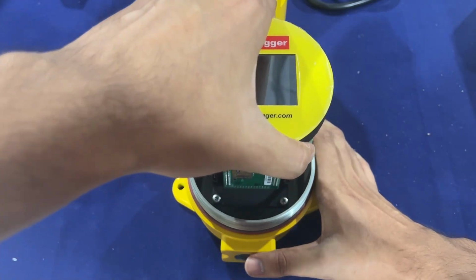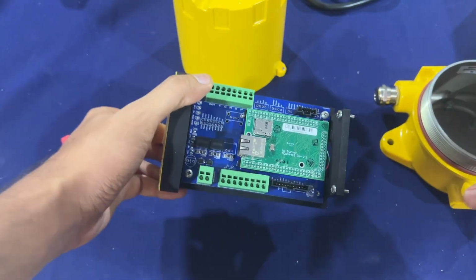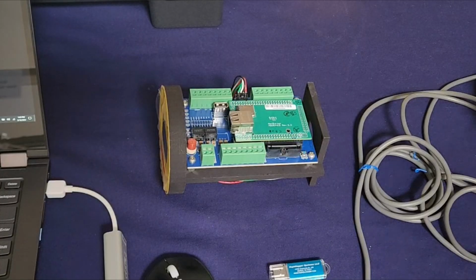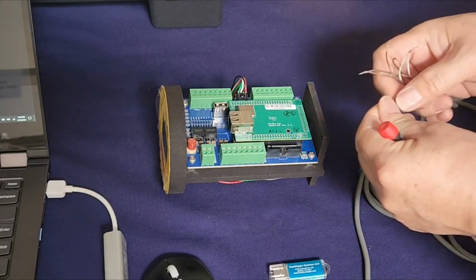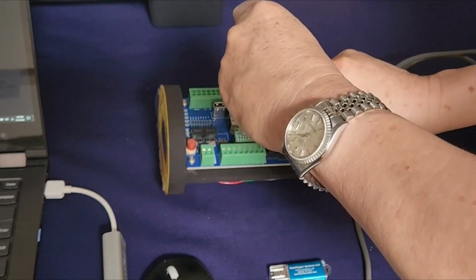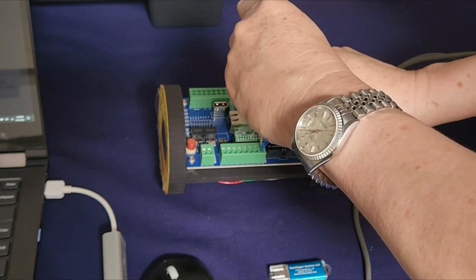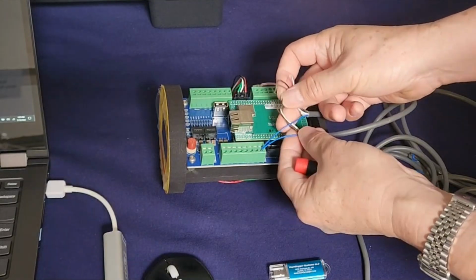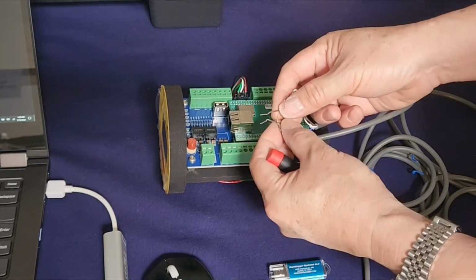Take out the Rapidlogger board and lay it on a workspace. Now, connect the encoder into the Rapidlogger ExD unit. To do this, connect the ground wire for power for both encoders into the terminal block J5-8. Then, connect the power wires for both encoders into the terminal block J5-6.